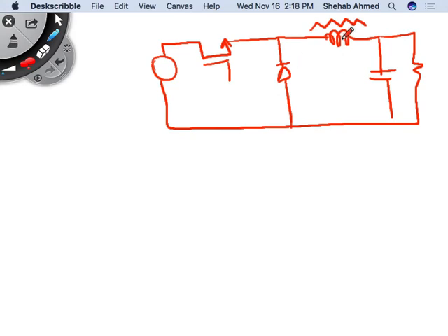Now with a switch, diode, and inductor, this inductor will have ripple current, depending on its size. If ripple current flows through the output load, what will the output voltage look like? The same ripple that the inductor has. So how do I reduce that? I add a capacitor.